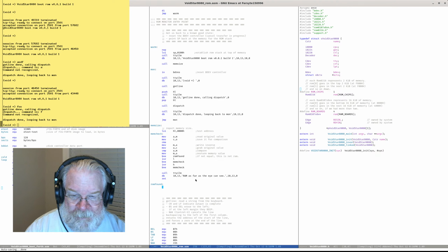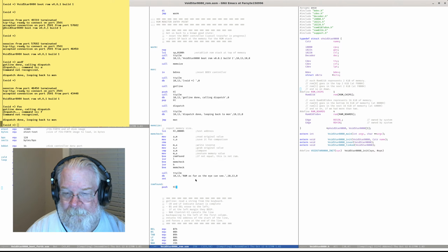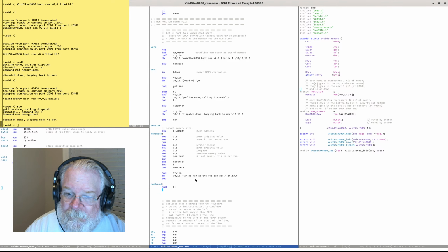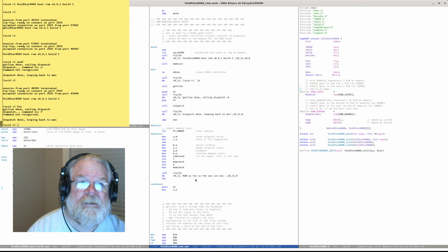So I want to print a bunch of characters. So first of all, push HL. And we have MOV A, H. I am going to print this in octal, I think.